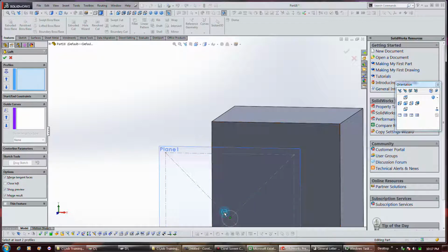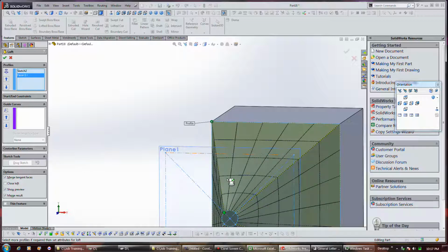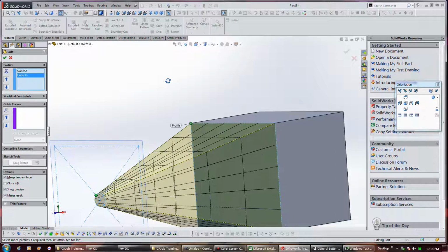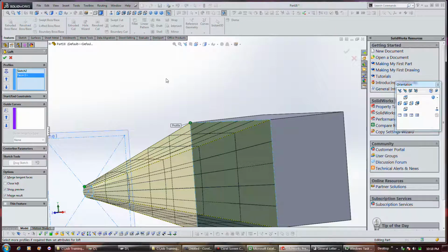I tried selecting this node and then selecting a point there, but the problem is it'll put it anywhere on the face. So apparently it works if I select a node and then click on a surface, but I can't click on an edge. I guess anything that highlights, if you click on it, it'll allow you to put the point anywhere you want on it. In the Loft command, what we're doing here, we're extruding the face of the cube to a circle here.